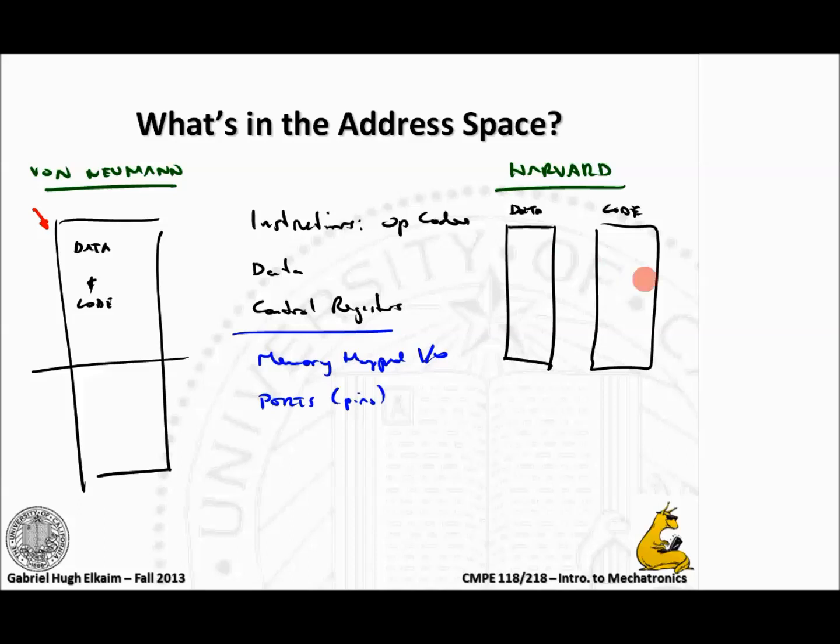There are some other reasons. So for instance, the Microchip PICs, the PIC32 is a Harvard architecture, and it has a completely separate data section and a completely separate code section, and what that allows them to do is make them different widths. So the data section is 32-bit wide, but the code section is actually 24-bit wide. The reason the code section is 24-bit wide is it allows them to fit all of their instruction codes in. It's a RISC architecture, and so they all get executed in essentially one clock cycle. And they all fit in perfectly. So that's one of the ways they do it. So there's a couple of advantages.